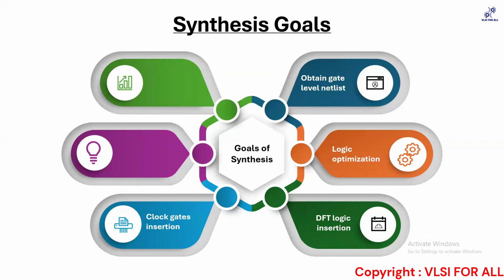Okay, ma'am. And then something which is clock gate insertion. Clock gate insertion can even happen at the PNR phase, but, for example, I would have explained it in my last lecture. You know what a clock gate essentially is. Clock gates are nothing but a way to gate the clock traversing your design. There is a special cell called the ICG cell which does this task.